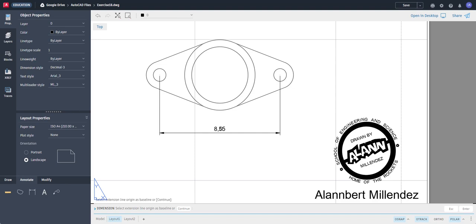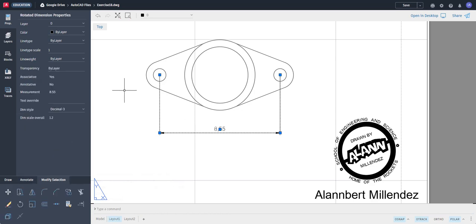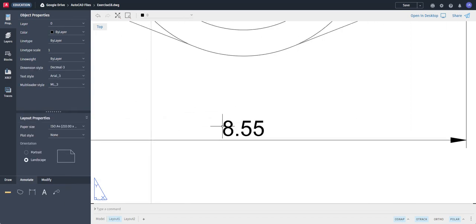So simply click that or press escape first, okay, to stop your dimension and then select 855 under your property. You will see here 8.55 is the measurement, but it shows it's 8 comma 55. If it does on your computer, you're going to go to this text override. You're going to click on it and then type inside there 8 period 55 and then press enter. Okay. So now press escape and now you will see that it override your decimal, your comma.